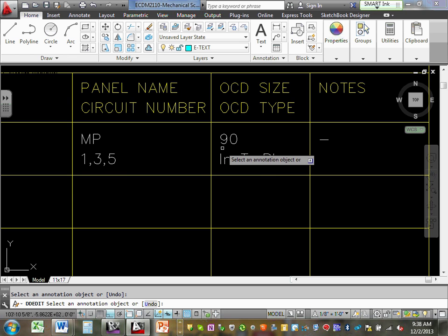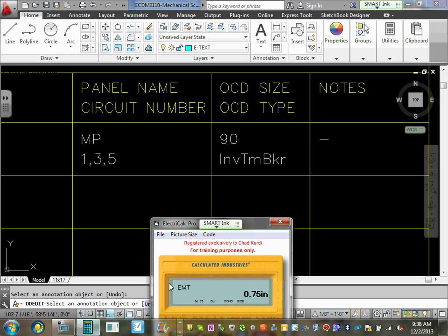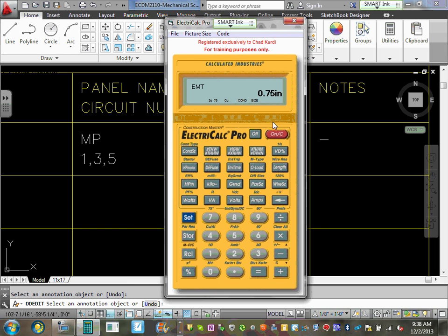Overcurrent protection device, Adam. Now, the overcurrent protection devices, guys, are going to be all circuit breakers. All circuit breakers. So the multiplier is 1.25. So how do we do that? Here's what you need to do. Go to the calculation that we did. So here's my amp. Oops, I forgot my amp now. Let's put this one again, 208 volt, and it's 15 horsepower. And the full load amp is 46.2.